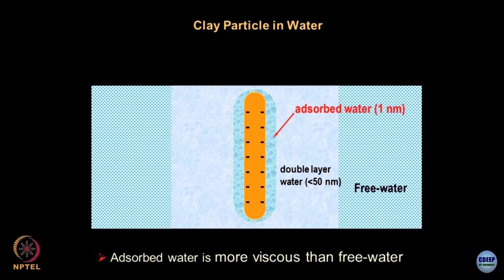Some time back you were asking this question about porosity and permeability. When we go into the micro details of permeability, we will discuss all these concepts again, and we will discuss why clays are less permeable as compared to sands. By virtue of their mineralogy, clay particles have a tendency to create an adsorbed layer of water, and when the adsorbed layers between two particles develop, the pore space becomes so small that no fluid can migrate through it.